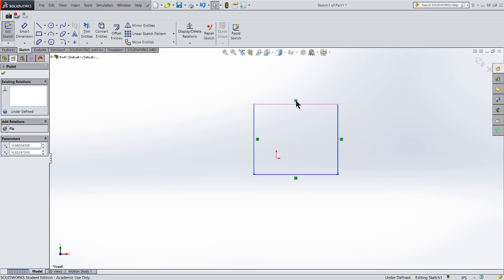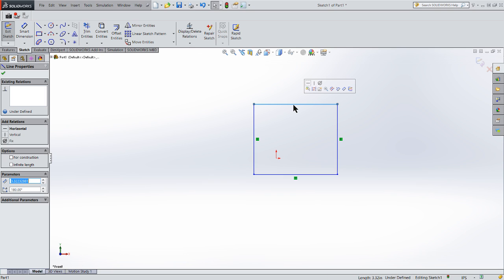So let's take another one of these, and all I'm going to do is click on it and delete it. And now you'll see that I took away that need for that particular line to be horizontal. And you can see how I can move that point up and down and all around. It's still got four sides. It is still a quadrilateral, but it's no longer a parallelogram. And even if I drop it so that it's horizontal, until I apply a horizontal restriction to it, it doesn't occur.